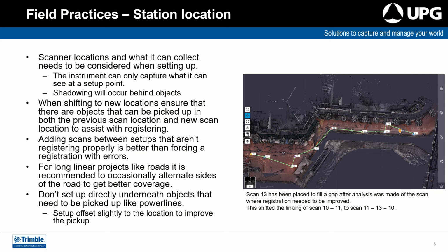Another consideration when scanning is that the scanner will not pick up data within a minimum range. So setting up within a doorway may result in some areas not being captured. So it's important to note how your scanner works and functions, and what the minimum and maximum distances are, when going out and when looking to set up a project.